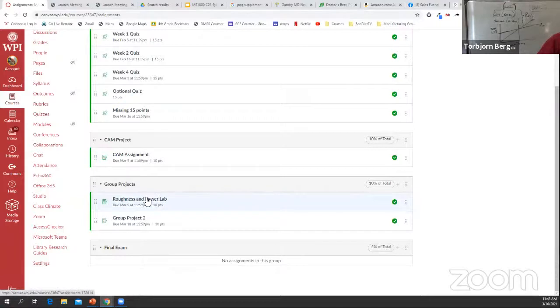There were a few of you that made the assumption somehow that the higher feed rate, which is the one that took more power, had the smallest chip. And it's the opposite. The one with the lowest feed rate has the smallest chip. So I took off a couple points on a couple of lab reports for having that mixed up.